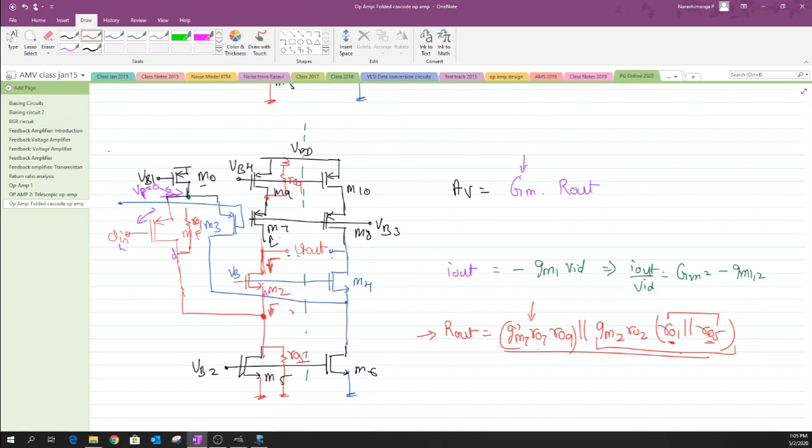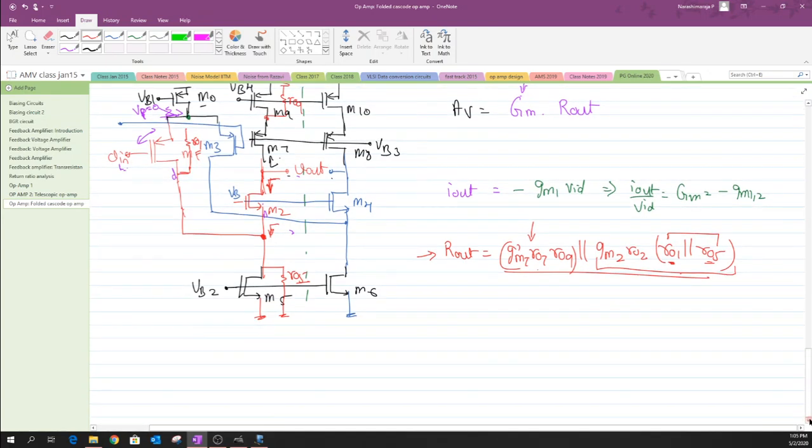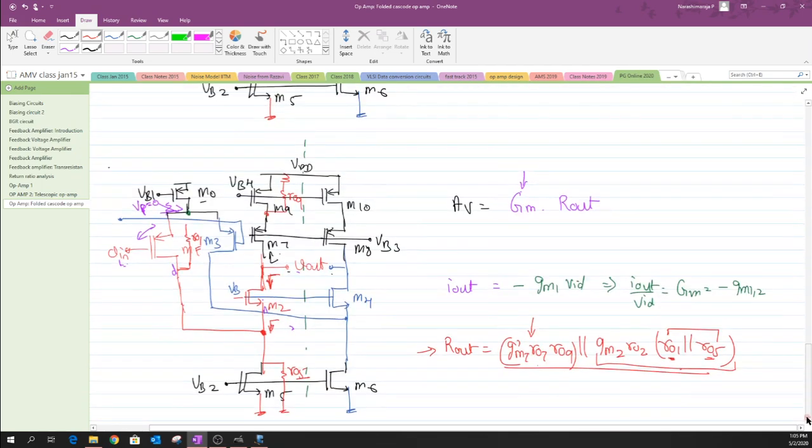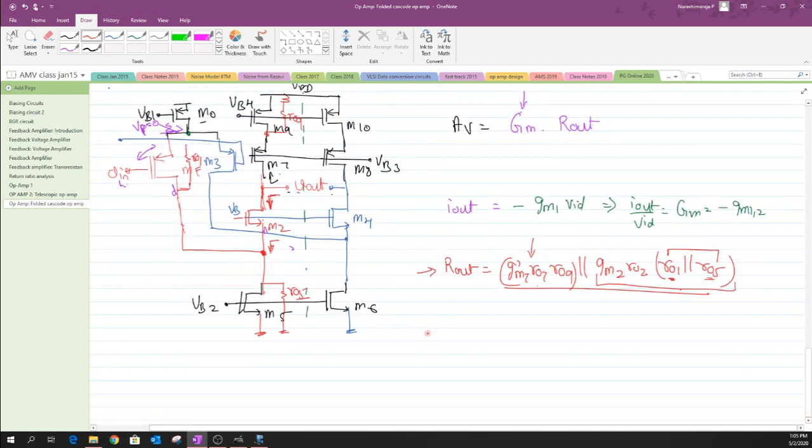Okay, so now let us try to do the analysis of output swing. Since we are talking about a differential output, we always have to have a factor of 2 multiplied by VO max minus VO minimum. Now let us evaluate the expression of VO max here.